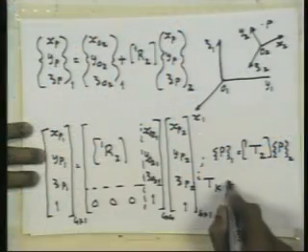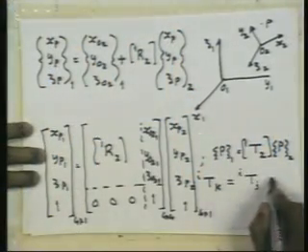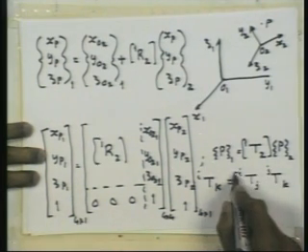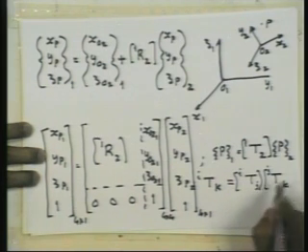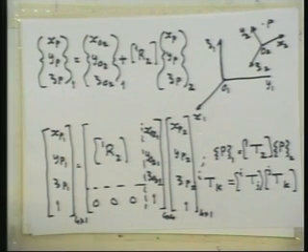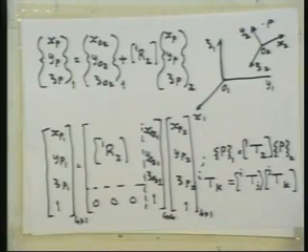So position and orientation of the kth body with respect to the ith body can be obtained from an intermediate transformation of the jth body with respect to the ith and then the kth body with respect to the jth. This actually makes the chain multiplication very compact.